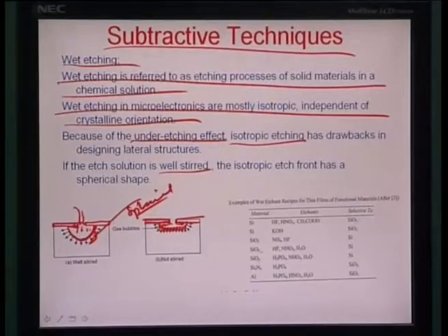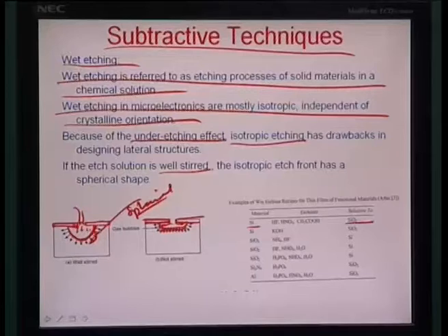Okay. So, another important factor here is the type of materials, and what it is selective to, and this has been illustrated earlier also, what you mean by etch selectivity. Selectivity is essentially the stopping process to the particular material. So, suppose in this case you have a silicon material and you have a SiO2 layer which is a masking layer or a sacrificial masking layer.